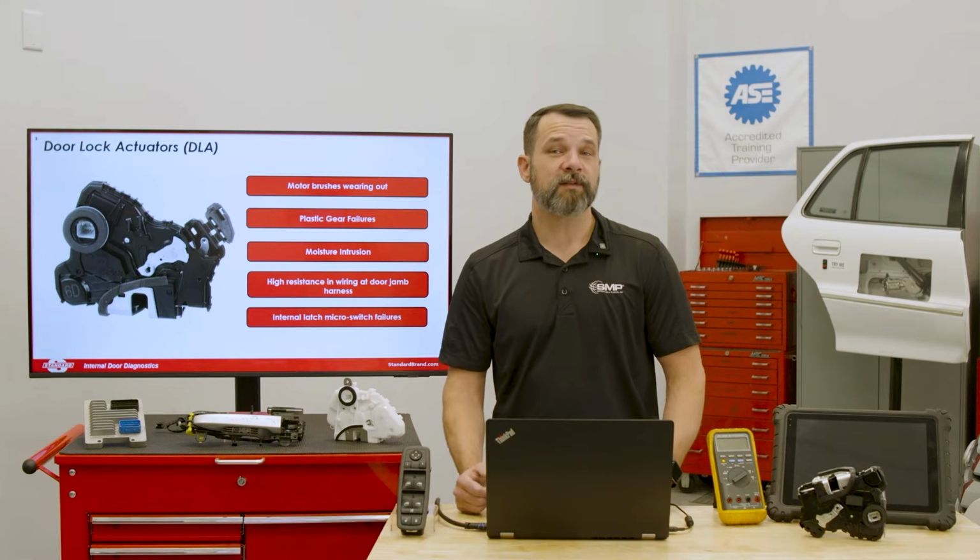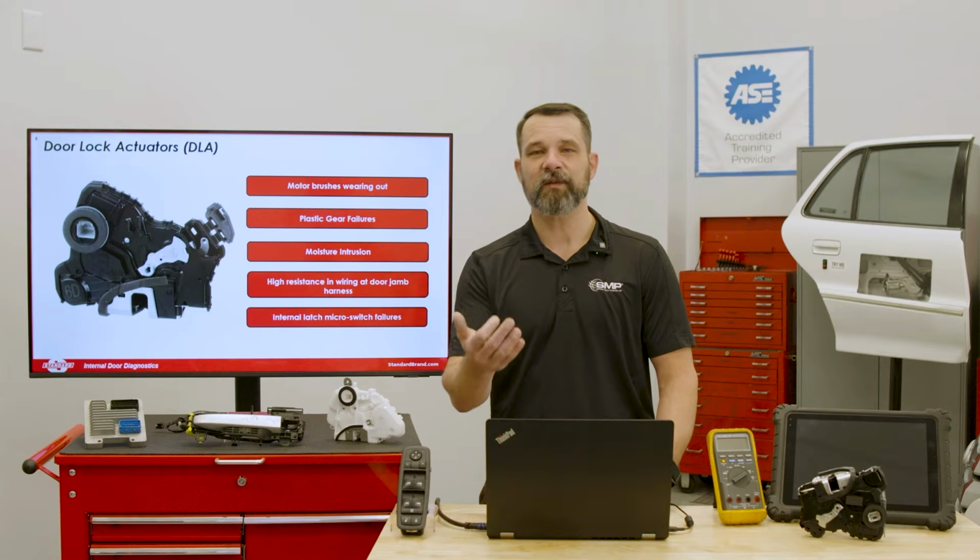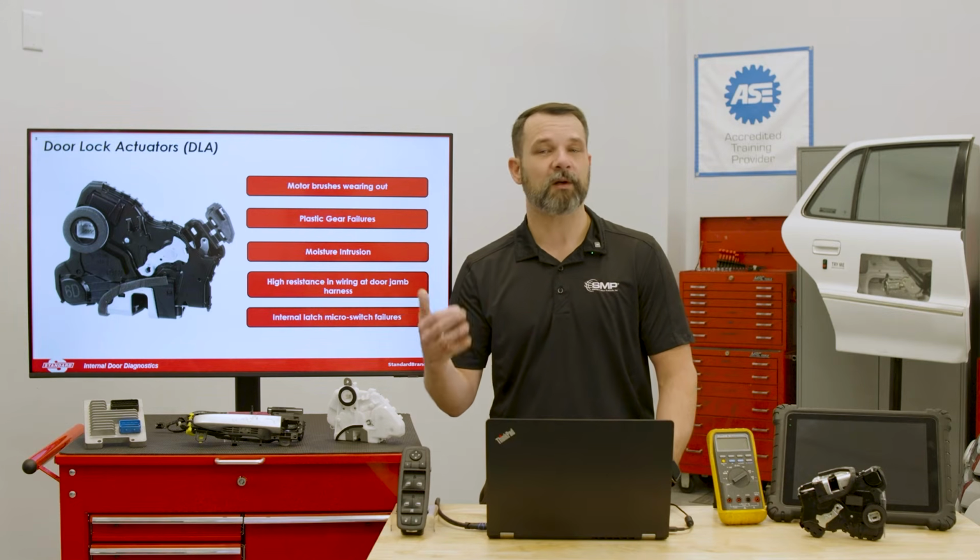And so some quick diagnostic tips here on door lock actuators, and this is not always perfect, but sometimes just listening for the actuator noise. Does it sound weak or completely silent?